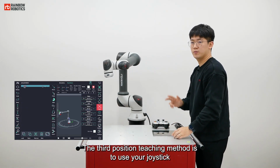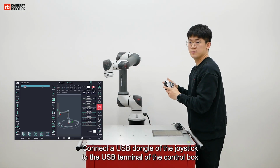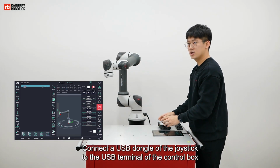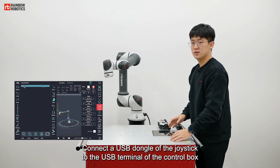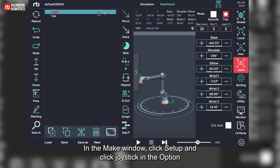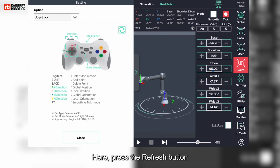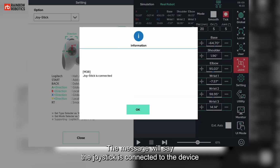The third position teaching method is to use your joystick. Connect a USB dongle of the joystick to the USB terminal of the control box. In the Make window, click Setup and click Joystick in the option. Here, press the refresh button. The message will say the joystick is connected to the device.